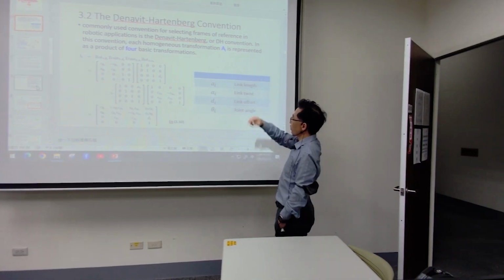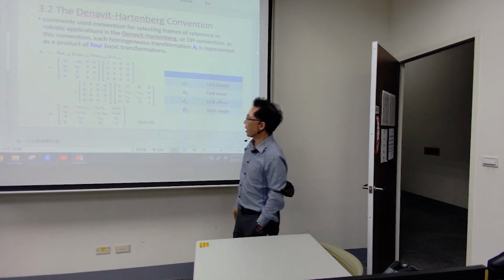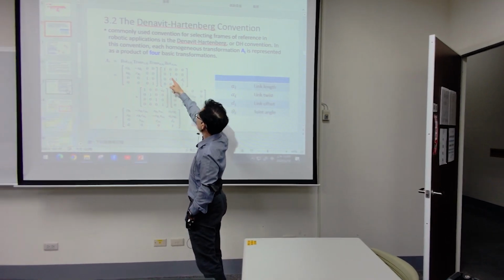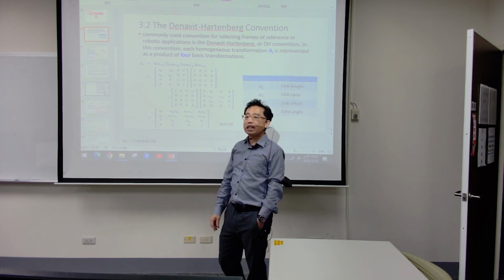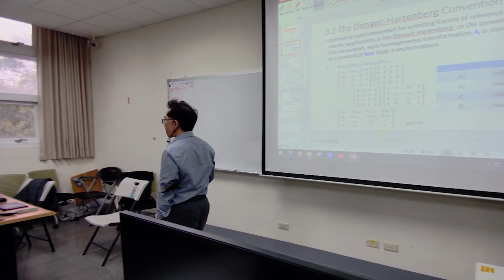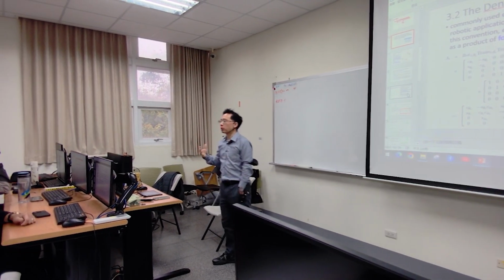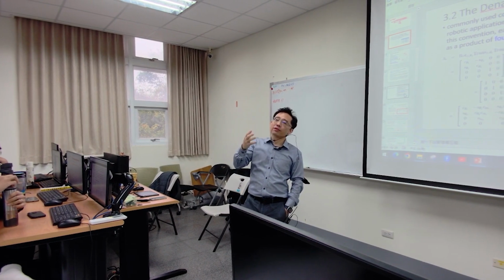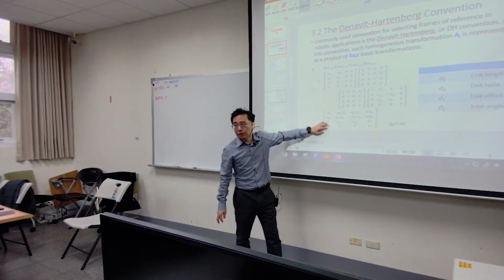Later on, the offset. I don't know where the offset is, or for the z axis. So the D is what you put into the z axis spot. Then you form the whole matrix, and then you can compute the final transformation matrix for one joint only. This is for one joint.